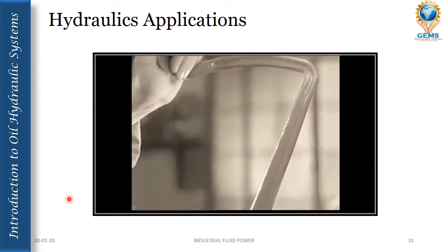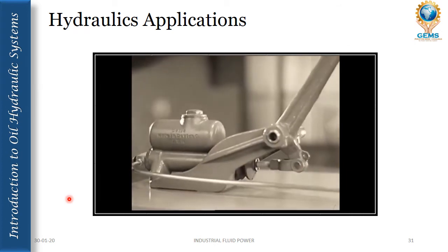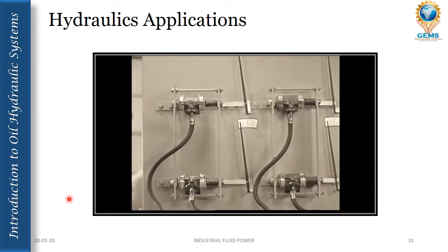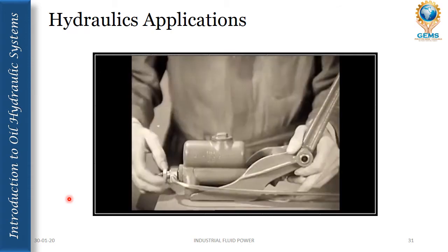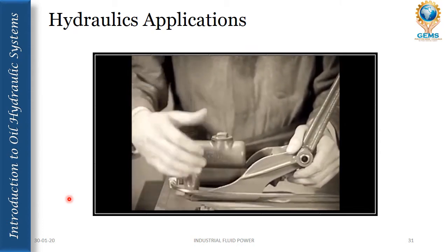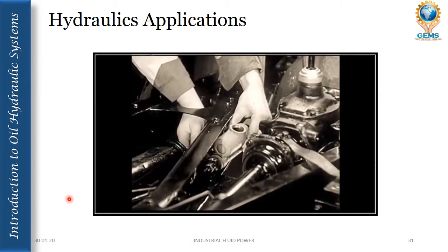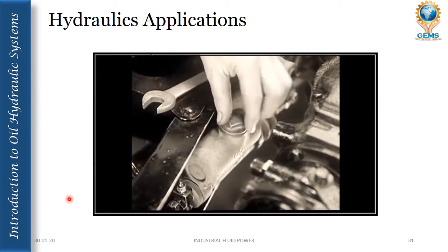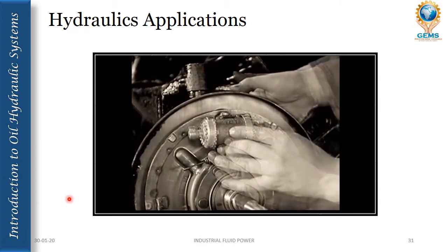In any hydraulic system, regardless of how many cylinders are attached to a master cylinder, each of the small cylinders receives the same amount of pressure and moves the same distance as the others. This principle is used in the latest application of hydraulic transfer of power, stopping the modern motor car. The master cylinder is placed under the brake pedal, and a power cylinder is put in the brake of each wheel.